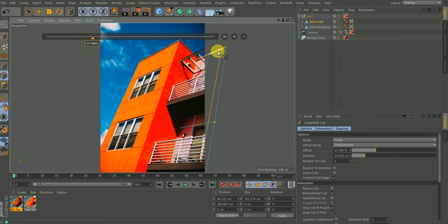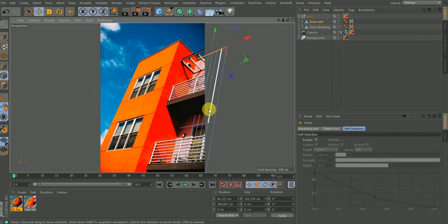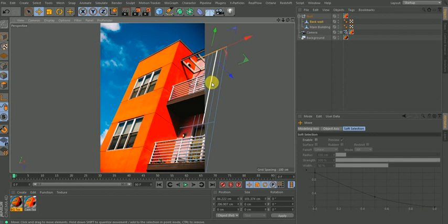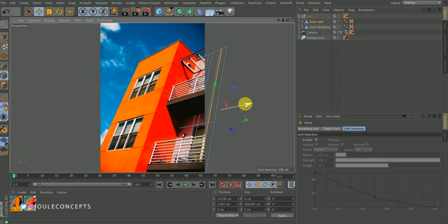So what if you're trying to get here and it's going off, just click anywhere. There's no problem with that. So you can just use your move tool. UL will do a loop select, or you could just double click on the line. It's going to select everything, so we move it close. So you double click on this also, move it in to have that. So I'm going to double click this, move it to get the frame of the door.